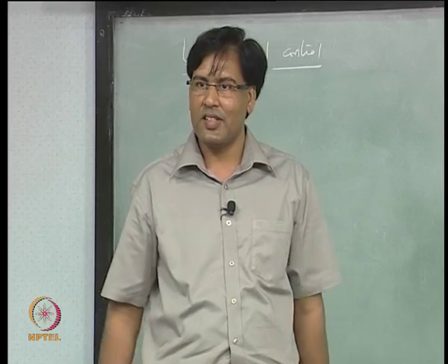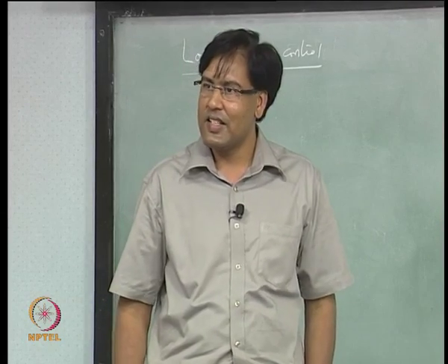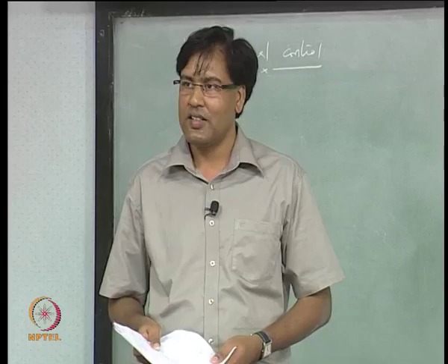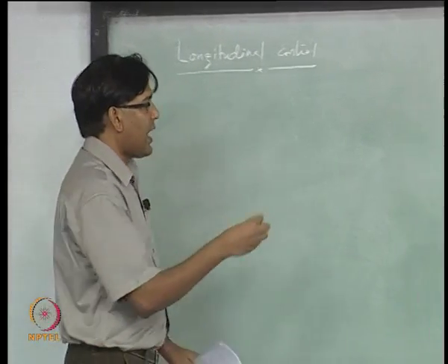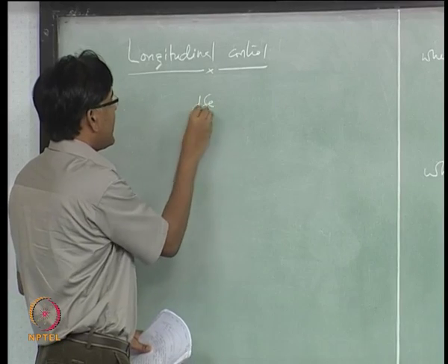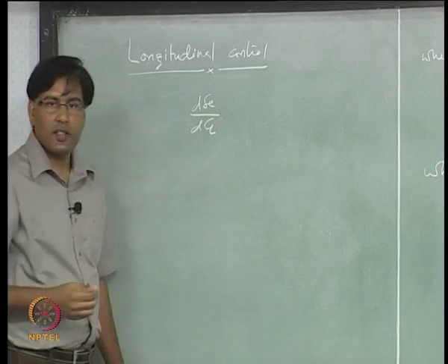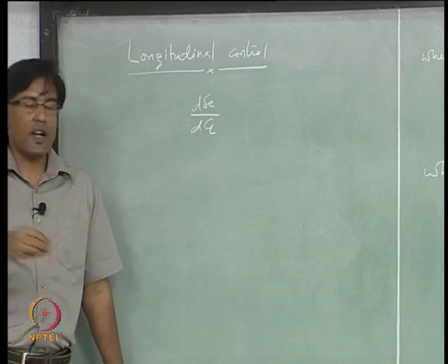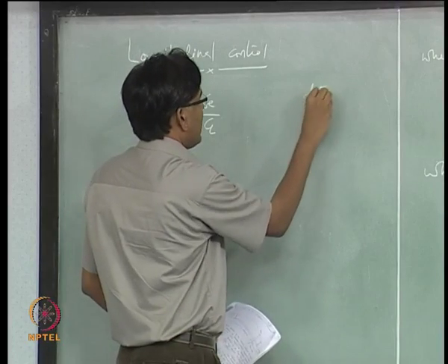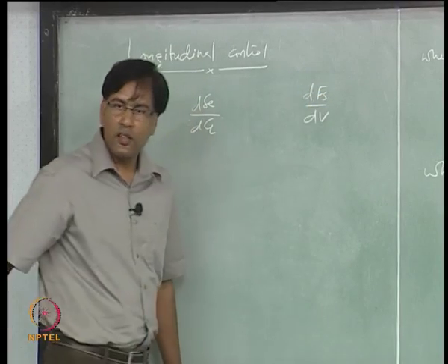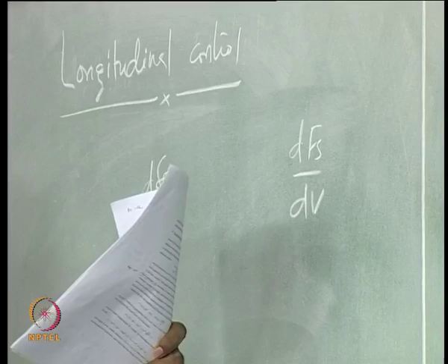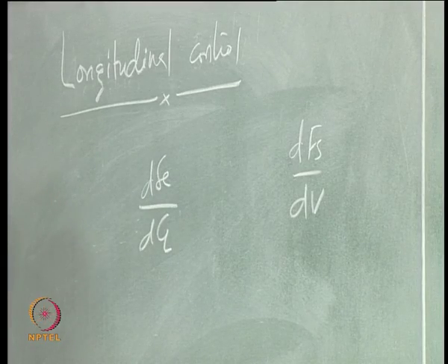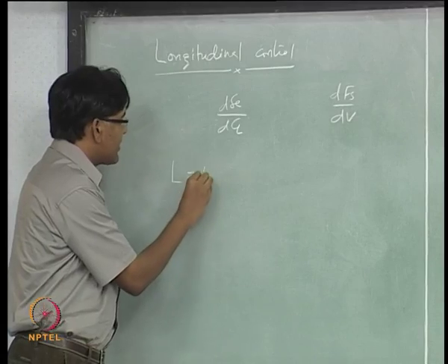Because we want to change the trim speed. We want to fly different speeds, right? So actually delta E over delta CL should also be somehow related to this, right, this gradient, isn't it? Because when you talk about a level flight condition,